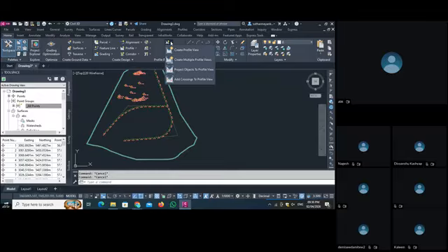So understand these things, then we go for the vertical curves. There are two types of vertical curve, crest and sag. When two different gradients meet, we provide a smooth curve instead of a sharp shape change. This makes a smooth connection, which we call the vertical curve.